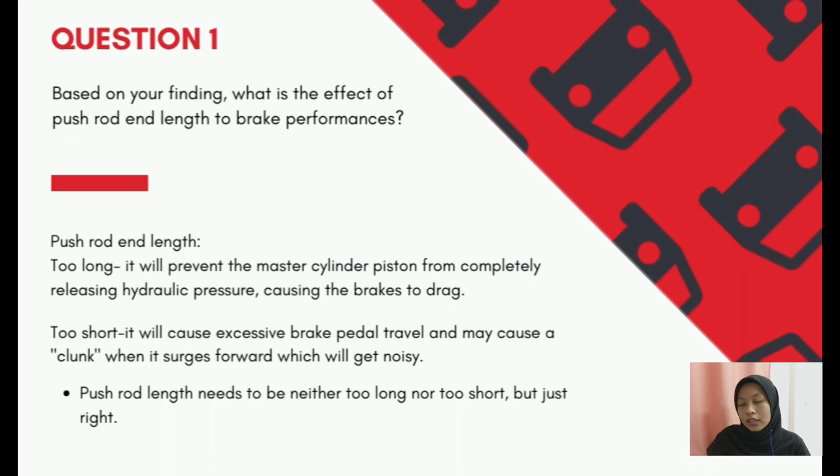But if the push rod is too short, it will cause excessive brake pedal travel, where the pedal will go down before the brake even engages, and this may cause a clunk noise when it surges forward.